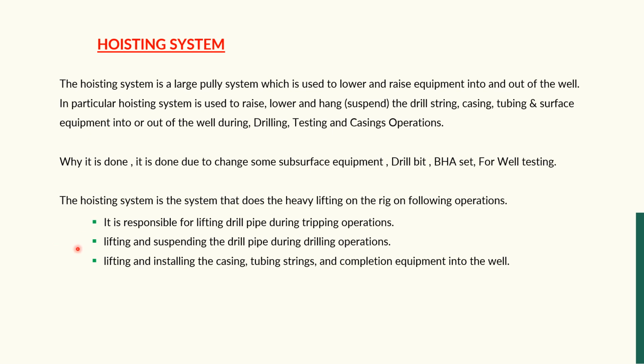I have further explained over here that the hoisting system is the system that does the heavy lifting on the rig in the following operations. It is responsible for lifting the drill pipe during the tripping operation. What is the tripping operation? Tripping is an operation when we have to pull out and run the drill string for a short time for changing any tool, for changing the drill bit, for changing the BHA set. We do the tripping.